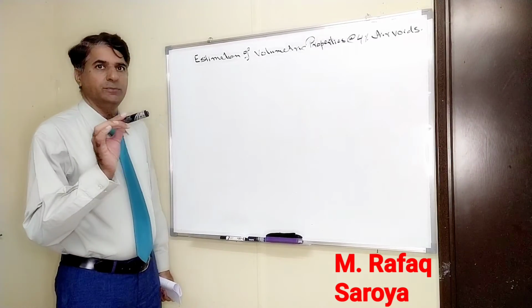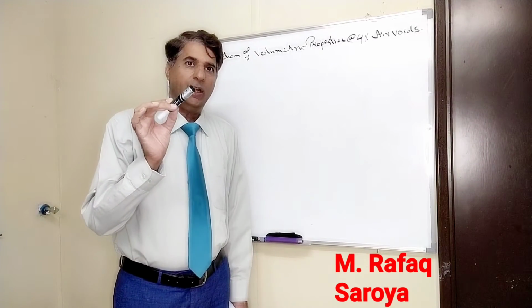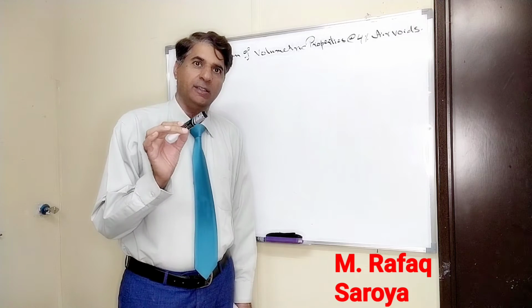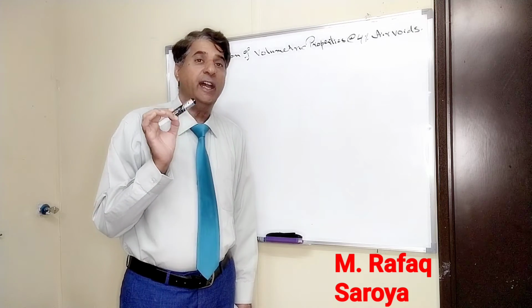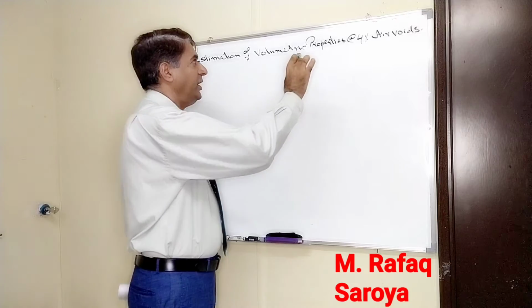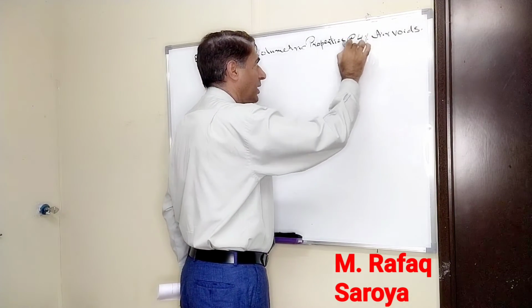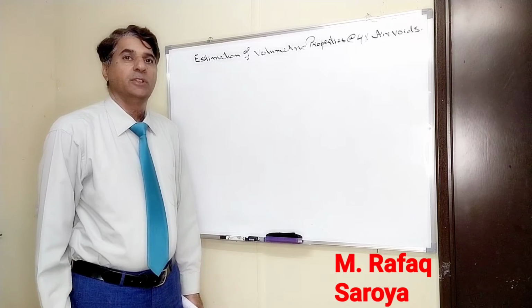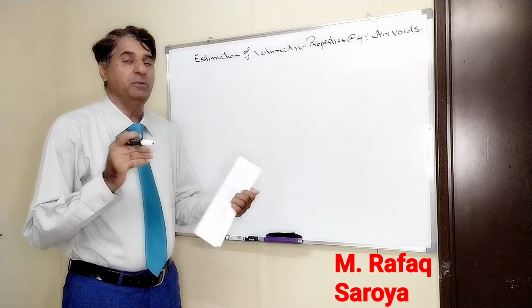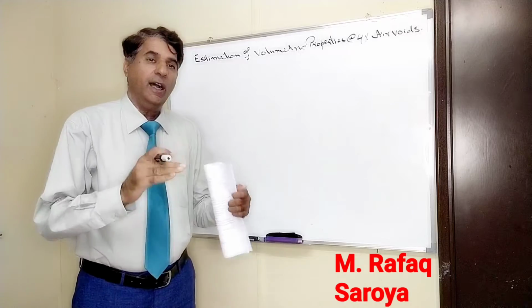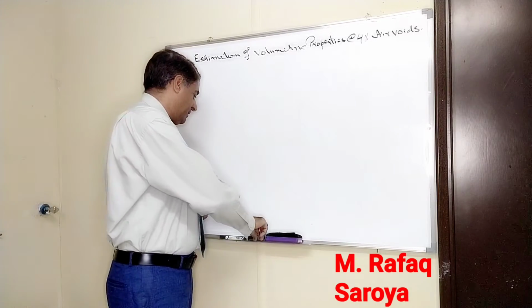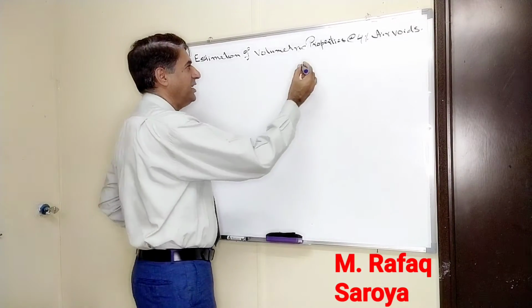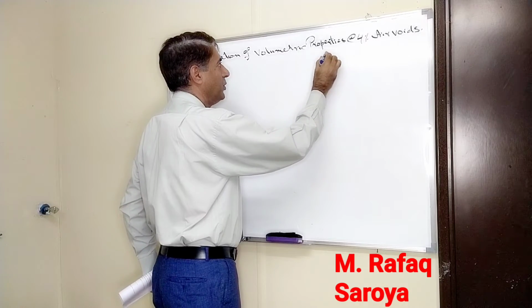Now, our Superpave method requires that the air void content should be 4%. So whatever calculation we have, for example, my specification says 4%